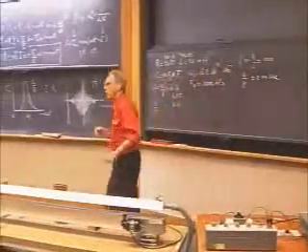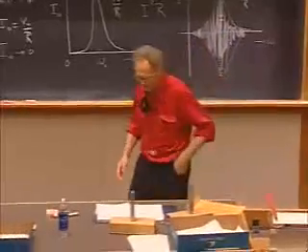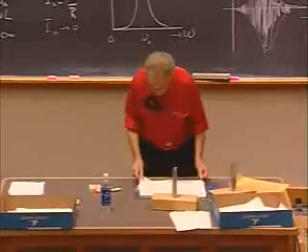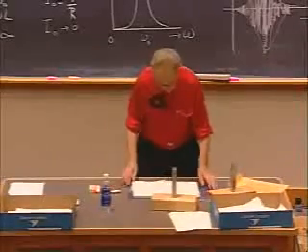So now I will make it 100 ohm. You see it's down by a factor of 2 from here to here. And you may have noticed that it also gets broader. And now I will go to 150 ohms. And you see it's down by a factor of 3. And again, it is broader. So this is an amazing way how with RLC circuits you can do wonderful things, because you can manipulate omega 0 very easily by changing L and C, and you can manipulate the driving frequency also very easily.